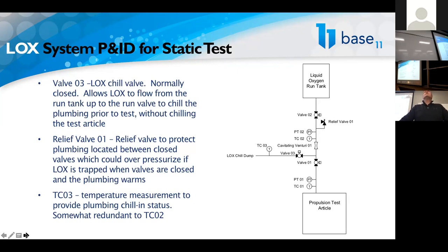And so obviously you need to make sure that the plumbing downstream can take whatever the momentum of the velocity of those fluids is. Are relief valves able to handle something as dynamic as a water hammer? I'm worried about risk with nitrous oxide vapor, adiabatic heating. If we put a relief valve in that line, is that going to crack in time? Using a relief valve to protect from water hammer would not be, in my opinion, a first choice. You want to prevent the water hammer in the first place.